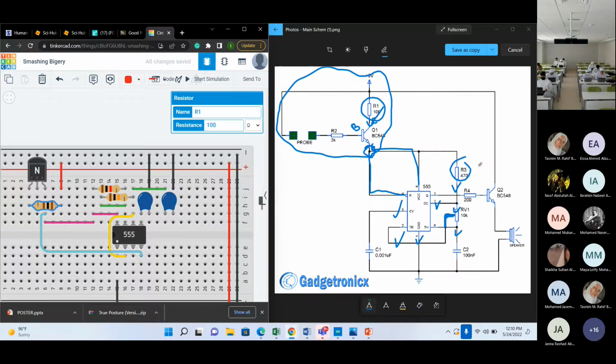If you check the previous resistors that we worked with, first of all, we had the resistor RV1 and the value of it was 10K. Which resistor was this? The one connected between pin 6 and pin 7. This is pin 6 here and this is pin 7. So it means that it was this resistor. Do you agree? And we already set it to 10K, so we're fine with this one here.